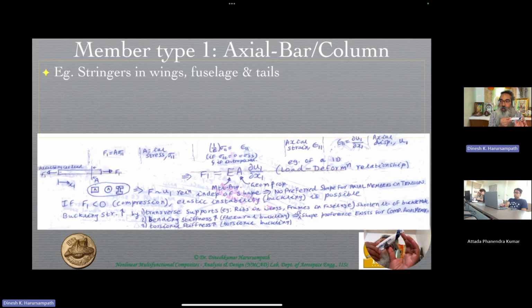And as we already indicated, this can be dealt with as a simply supported beam, supported at the wing and the horizontal tail. We will also have an overhang from the wing onwards towards the nose of a conventional aircraft. Many aircraft will also have a canard, which means you have a triple support. The overhang will not be too much in that case. Okay, so that's the example.